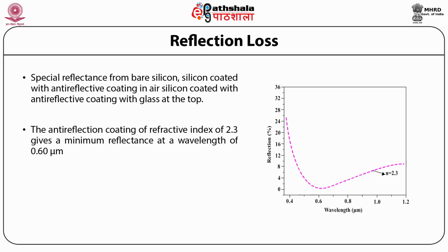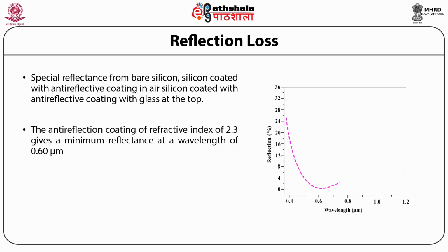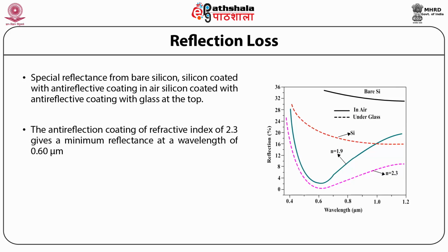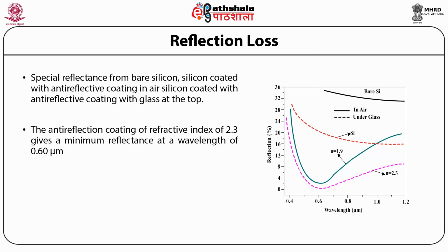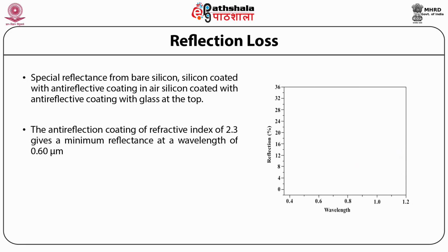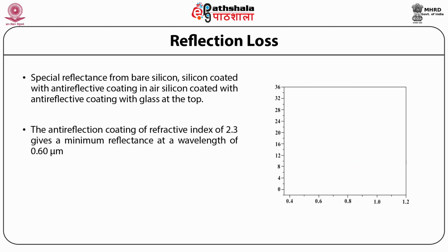The chemical etching of the semiconductor surface gives an appearance of pyramids on the cell's surface, where the light reflected from the face of the pyramids is directed towards the cell, and therefore the light has at least two chances of being coupled into the cell.